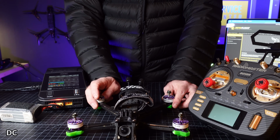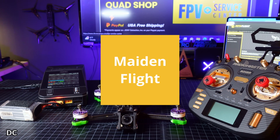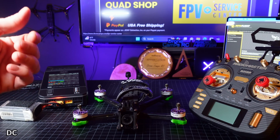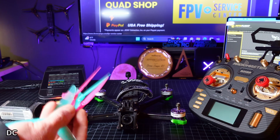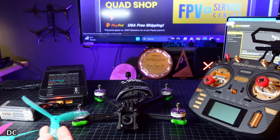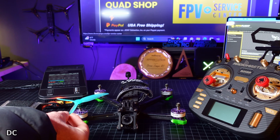Now, things that can go wrong, let's talk about that. Things that can go wrong on your maiden flight, 9 times out of 10, it has to do with 2 things: motor direction, or you have the wrong prop on the wrong motor. And this even happens to me still years later. These propellers, they all kind of look different when they're all in a pile like this. So when you're putting them on, it's very important to pay attention to which direction of travel you're putting them on, and that it's on the right motor.